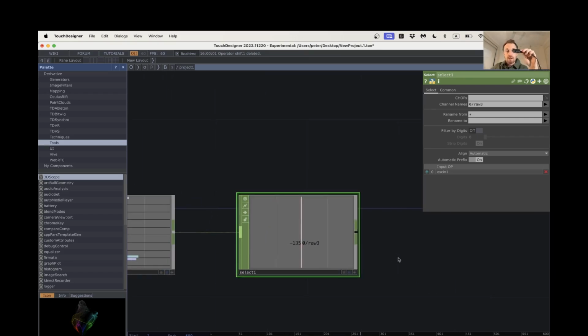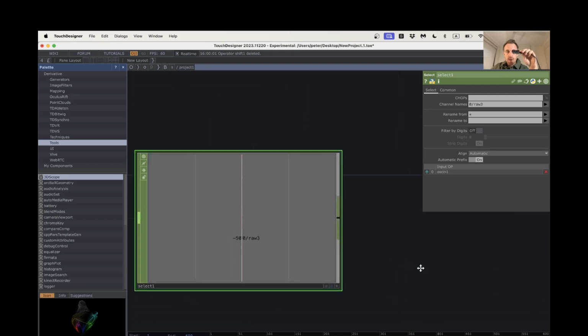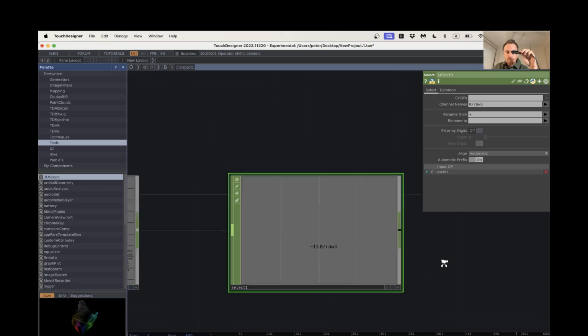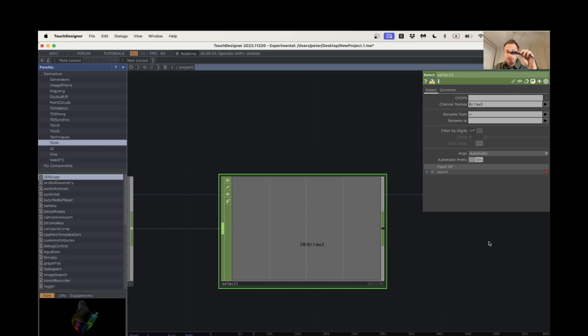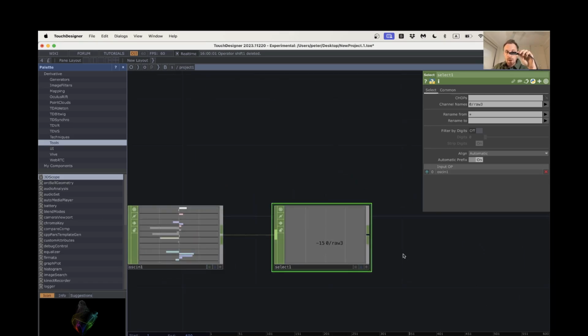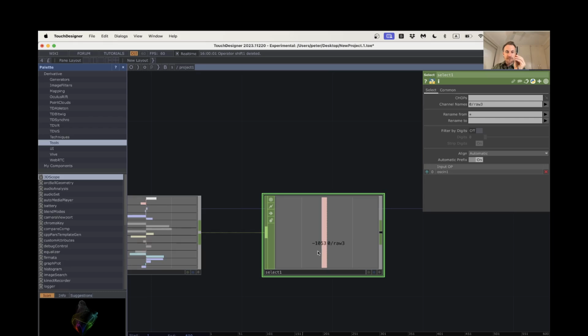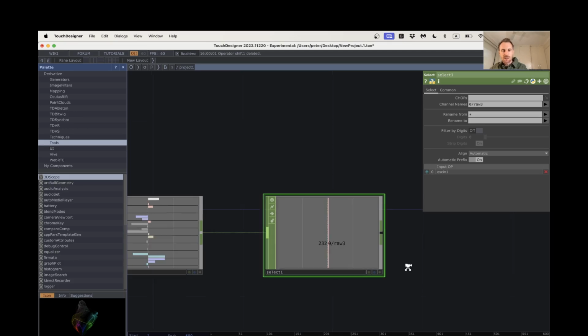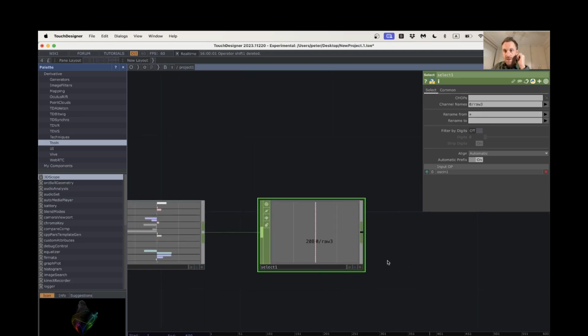The next thing is we're going to want to map this onto values for something else. In order to do that, we want to understand what range we're working with. So if I move the tile to a vertical position, you'll see that it maxes out around -1000. And if I rotate it the other way, it's about +1000, give or take. What I tend to start with, depending on how accurate I need to be, is to take that as my starting range.